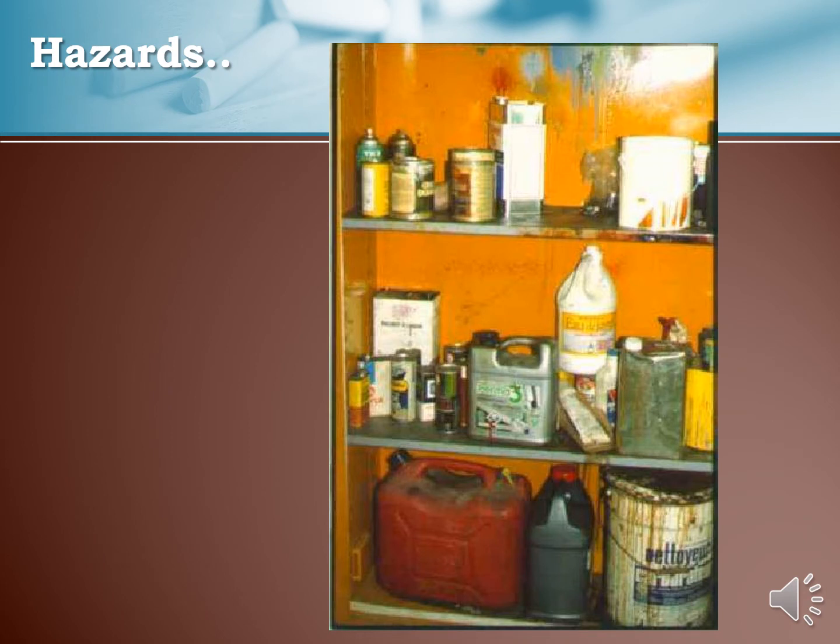Here are a few examples of the types of chemical hazards you might note in an inspection. Starting on the bottom shelf. This gas can is approved for gas storage in this context, as it is stored inside of a flammables cabinet. However, there is a yellow gas cap missing from this can, so it's venting into the cabinet presently.